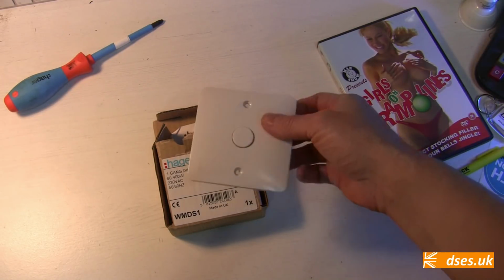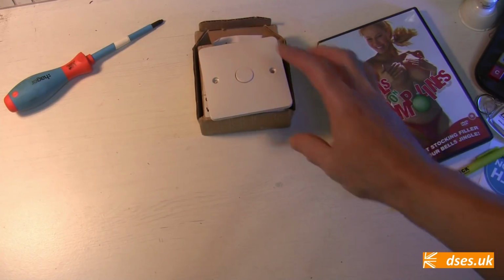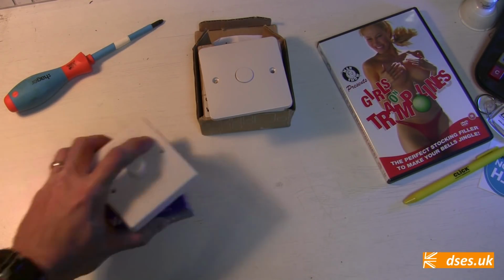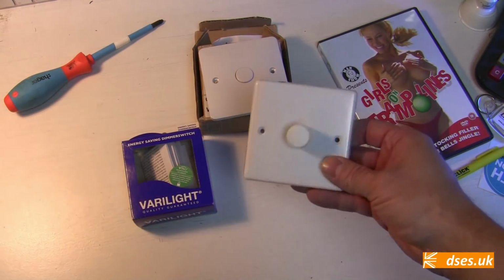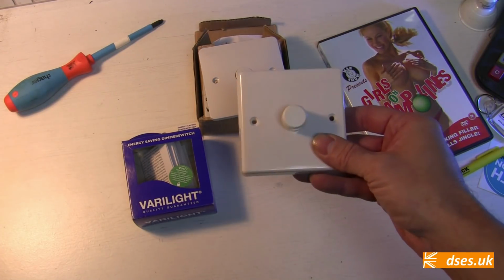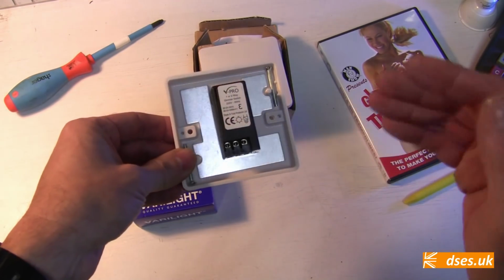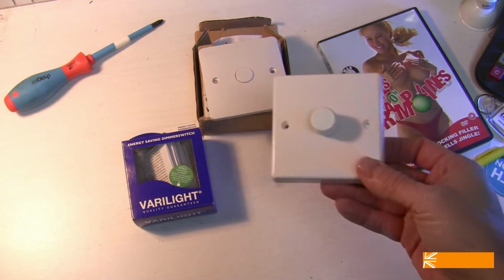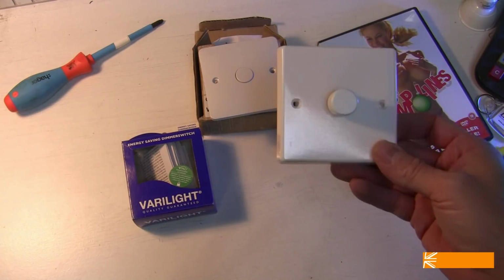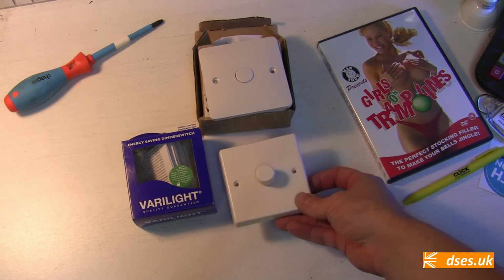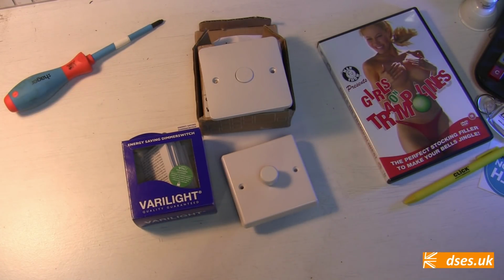You may need to change your dimmer for one specifically designed to work with LEDs, such as this Vari-Light V Pro. The V Pro has no minimum load and is also programmable, so if your LED lamps aren't playing properly with it, then you can set it to a different driving mode which may be more compatible. Switching your switch to one that is LED compatible may be the answer if your existing switch predates LEDs and is anything other than a straight mechanical on-off affair.